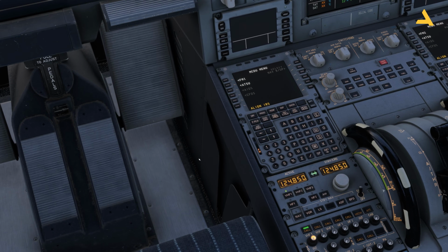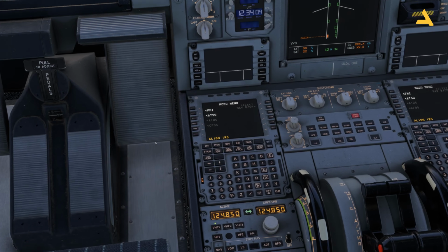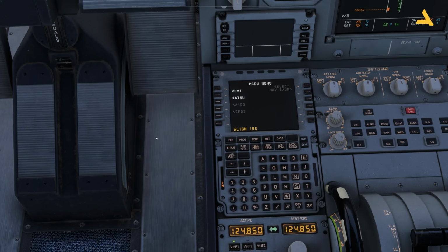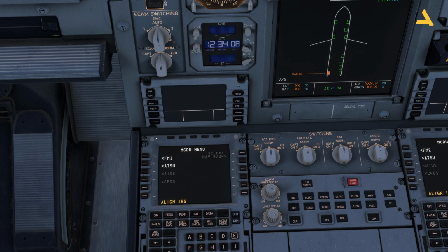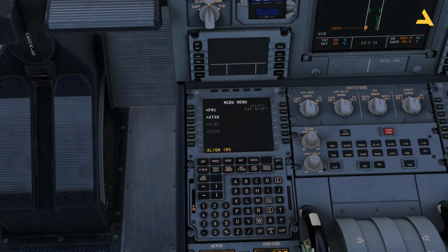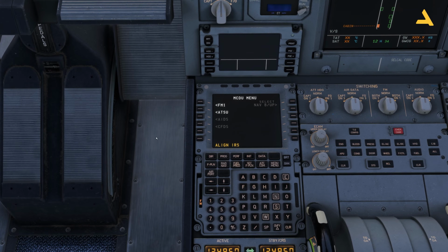That's it. Now this is the MCDU, which is the multifunction control and display unit. So after configuring the EFB, you have to get the flight plan over here. There is a procedure to configure this MCDU. This is known as the DIFF strip data. You have to then do initialization, flight plan, secondary flight plan, RadNav, initialization B, and performance. So I will just take you through all these steps.